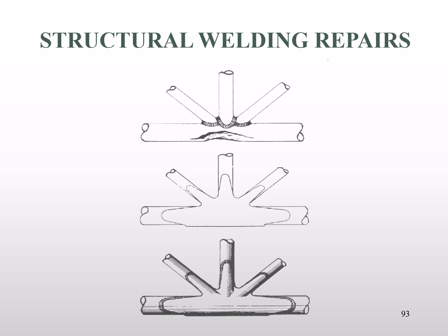But as you can see here, if we cut this out, we're going to cut actually 4 tubes loose all at once. It is acceptable, and the right answer to the question, and this is the question, what can be done at a dented steel tube cluster joint? Well, we can weld on a repair patch, or old timers call them finger patches. We actually reinforce over the existing tubes with a steel patch that reestablishes the strength and reduces the complexity of that welded repair. Question asked, question answered.